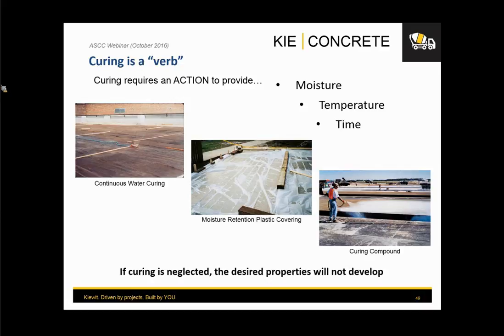Like sometimes in bridge decks, that's the way they do it in New York. They tell us you have to go with curing compound. That will be the first step you're going to do, and then after that, you're going to implement 7 days of water curing.